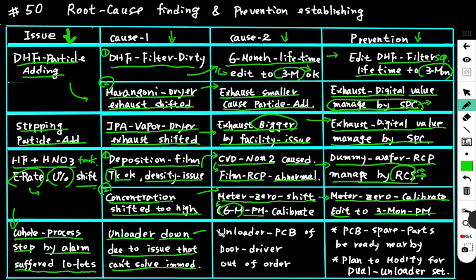And according to this root cause, we got root cause 2. The unloader PC board, the PC board of the door driver, was out of order. Checking the PC board job, we found the spare part took a very long time. It let the unloader down and could not be solved immediately, and 10 lots of wafers suffered.